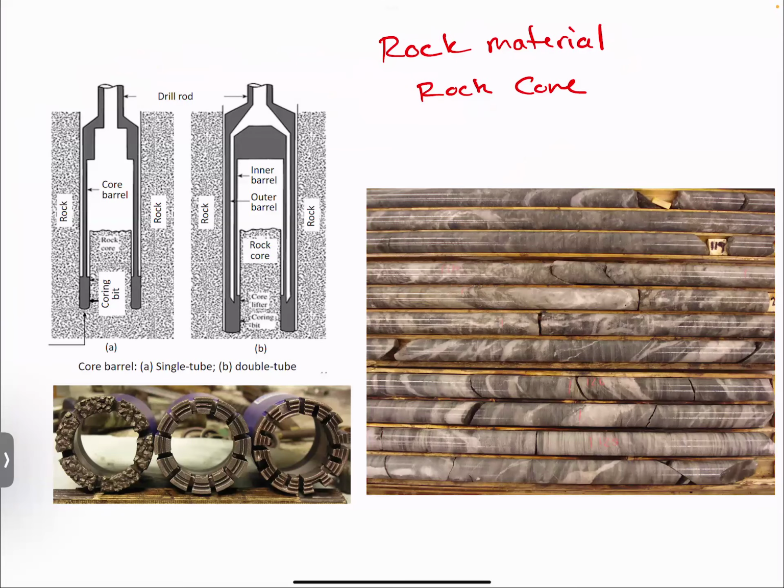The other types of things too, we have rock cores, and this allows us to bring samples of rocks up to the surface. This is really cool technology. I forgot the name, like wireline or triple tube or something. You can have a rock core where the outside or the whole thing moves, which causes a lot of friction, but now you also have double tubed, where the outside drills down and then the inside will actually drill, and you're able to get some of those really clear looking sections there. And then obviously the drill bit is important too. And this would have to have a good understanding of the geologic condition and the contractor there.